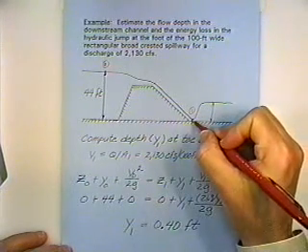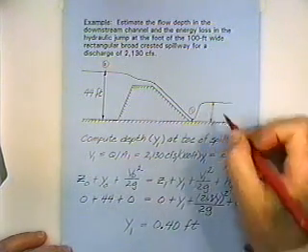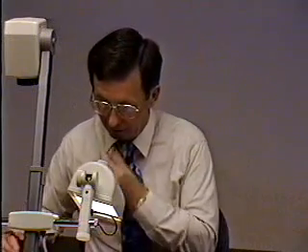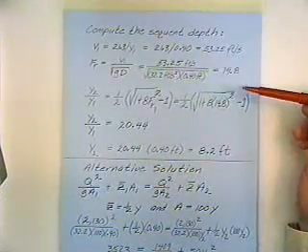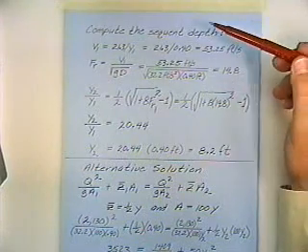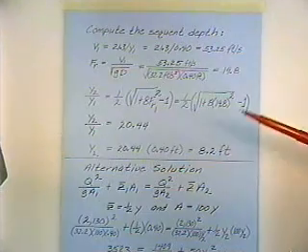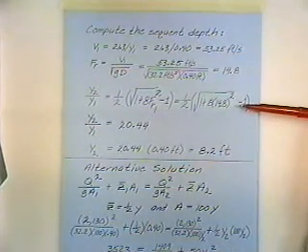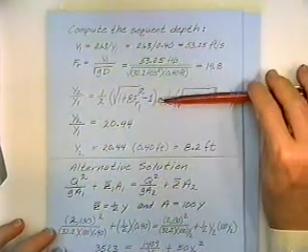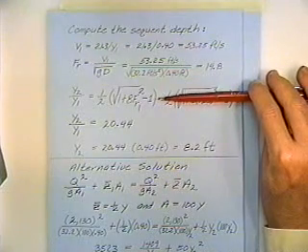Knowing the depth here is 0.4 feet, we want to get the depth here using conservation of momentum. In other words, we want to compute the sequent depth. And so I'll use this basic equation. Here's the basic equation reproduced from the previous page of the notes.